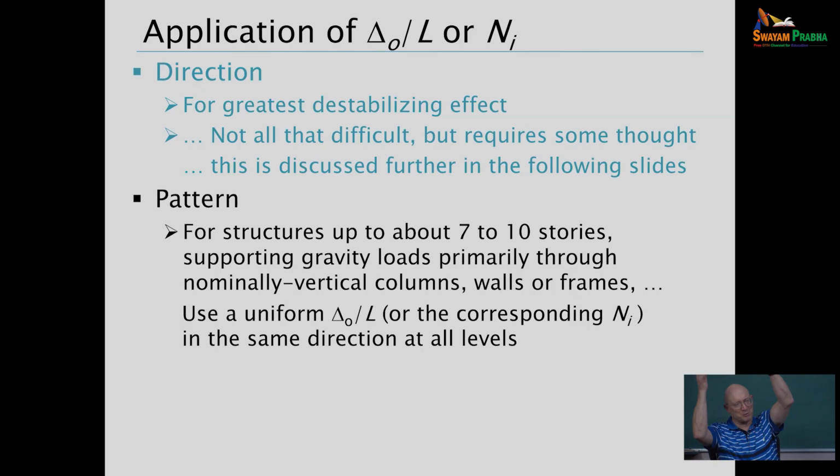If it's a very tall structure, that's an awful big lean after a while. And in a tall building, they're going to have better tolerance than that on the overall verticality of the frame over the entire height of the building. So that kind of gets a special situation. But for most routine things, less than 7 to 10 stories, we just put a uniform lean on the entire building.